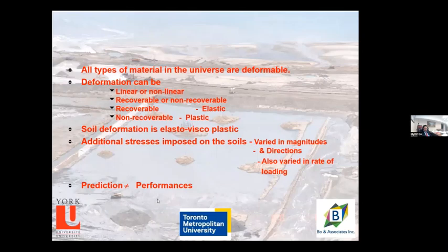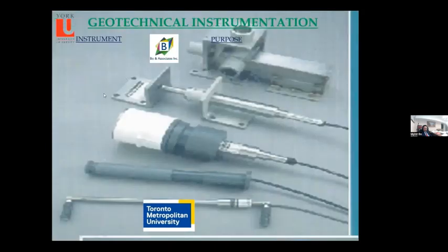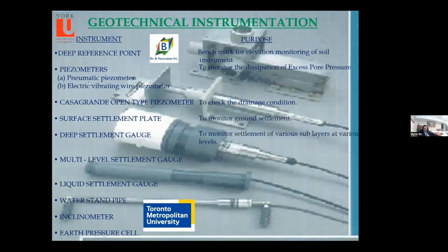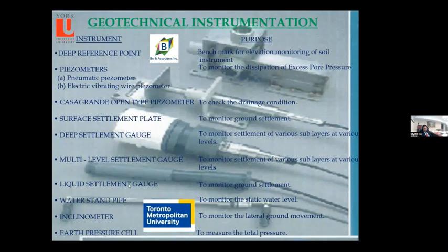So in order to fine-tune, geotechnical engineers developed the observational methods. For that, geotechnical instrumentations like piezometers, settlement gauges, and inclinometers, uplift pressure gauges, etc. were developed.